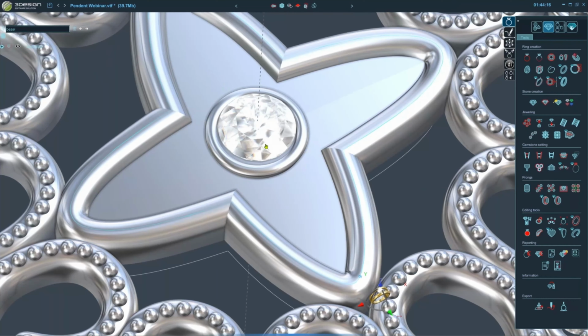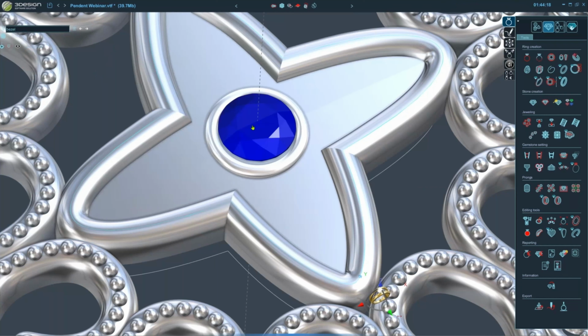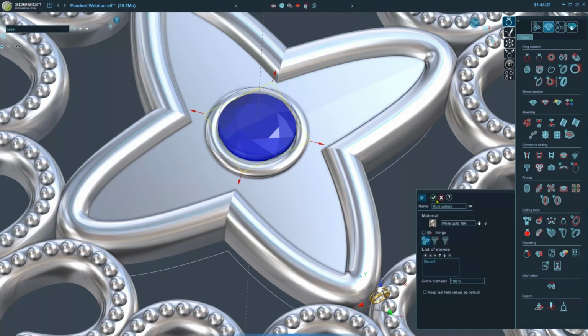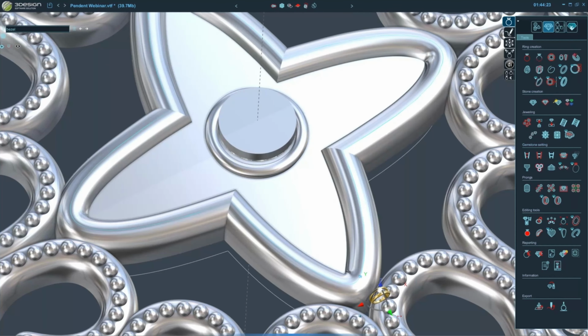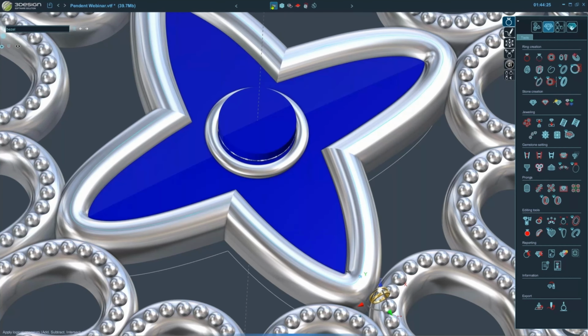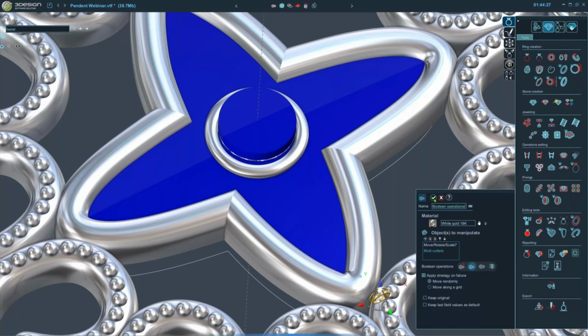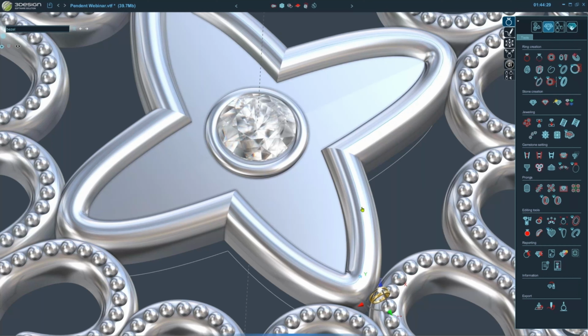Okay. And then because of that plate behind here, I do need to quickly do a multi-cutter here. And I'm just going to use the default shape to subtract that cutter for the hole behind the stone. Yes, I created that surface pullback from the projected curve. Since I couldn't extrude a projected curve because it's no longer planar, it's based on the surface, that's where you want to use a surface pullback instead.